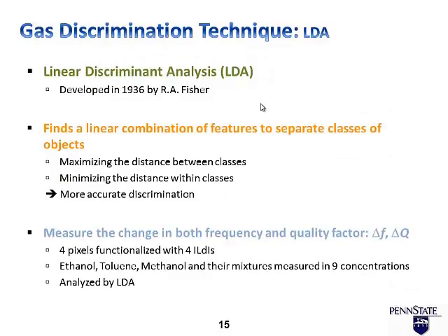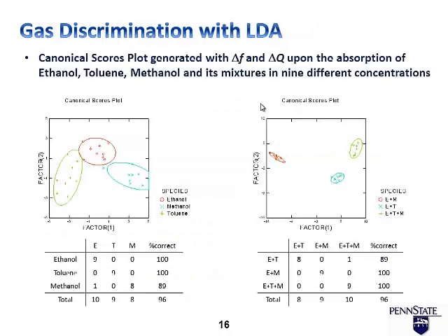So finally, we use the LDA technique, which is also one of the techniques of pattern recognition. We use this technique to see how we can discriminate the mixtures of the VOCs. The results here show a very high recognition rate for recognizing individual gases and its binary and ternary mixtures.